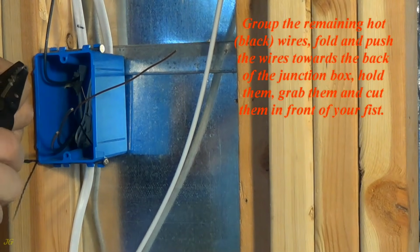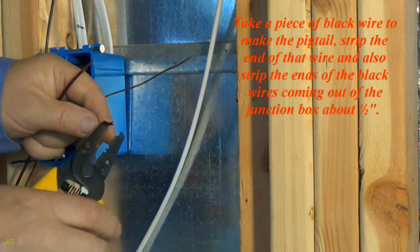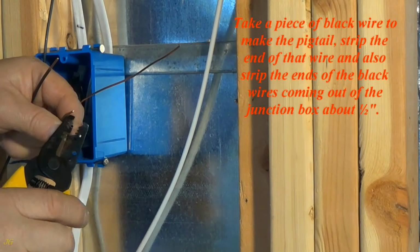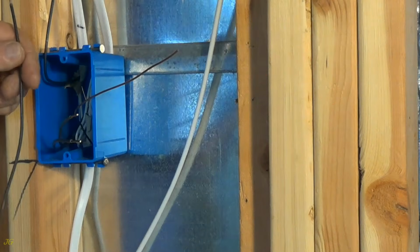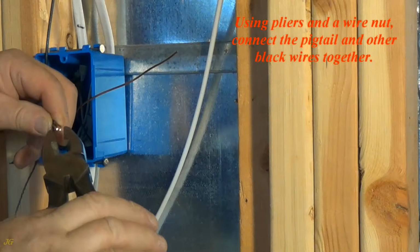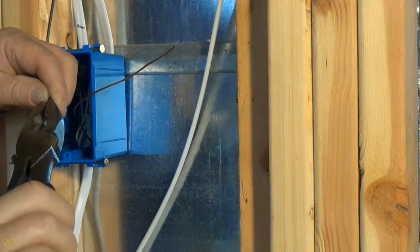Hold them, grab them and cut them in front of your fist. Take a piece of black wire to make the pigtail. Strip the end of that wire and also strip the ends of the black wires coming out of the junction box about 1/2 inch. Using pliers and a wire nut, connect the pigtail and other black wires together.